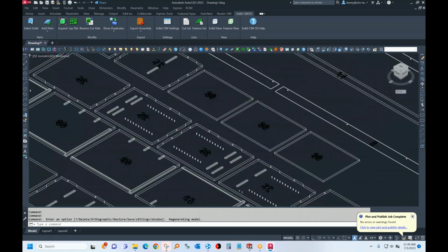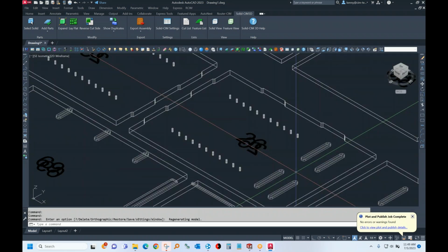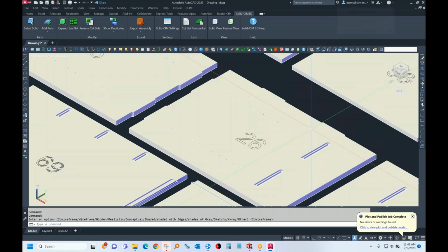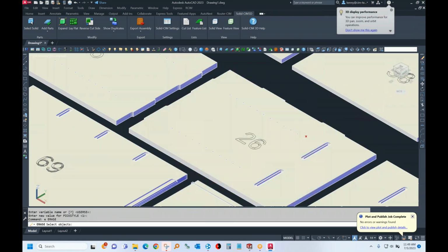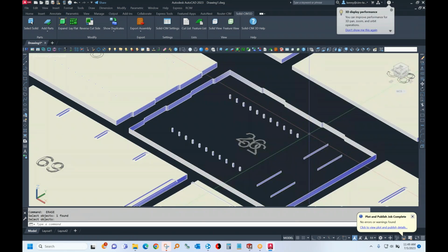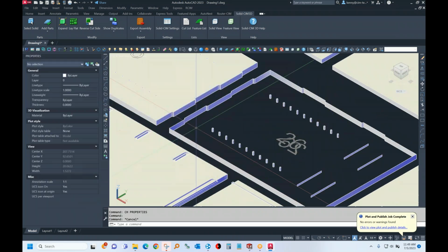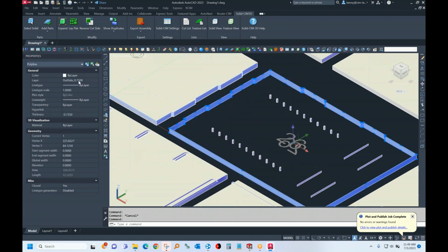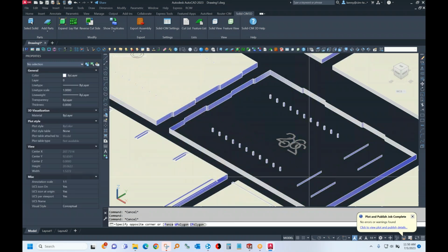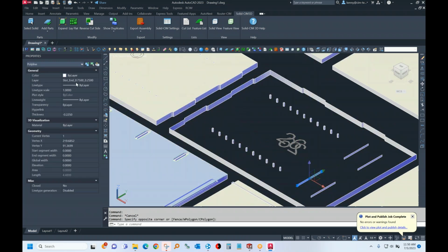A lot of people will gasp right there and say, oh my God, that took me forever to do that. And here you can see the automatic feature recognition and what's created here. If we turn on the shaded view, I can erase the solid, for example. And there you can see stuff on layer hole. It's got the diameter and the depth, and it's got the thickness, so Router-CIM knows how deep to cut it. Here's layer outside. And here are some slots. There was something on layer slot, and that's the depth, right?